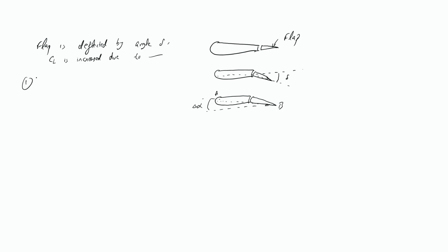The first reason is that as the flap is deflected, you can see the camber of the airfoil section has increased. The more the camber, the higher the CL.